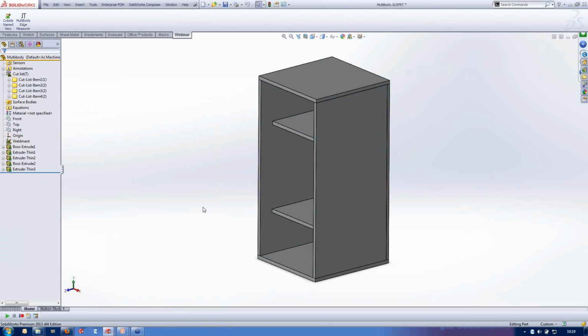And then having a look at the code that it produces and also what it can do for us. So what we're going to do is we're going to start recording a macro. Very simple, macro toolbar up. Let's choose record pause macro. So we're going to choose record.